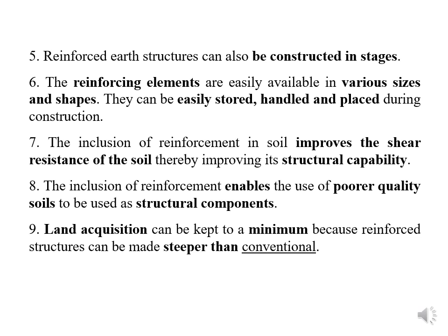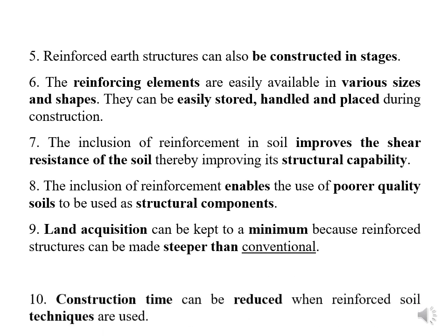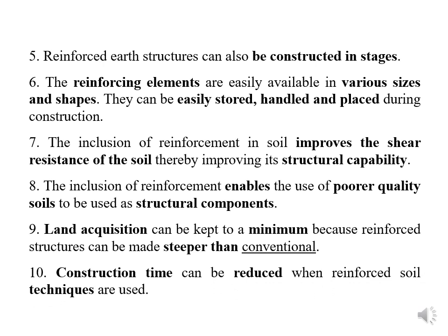Land acquisition can be kept to a minimum. What does it mean? If you construct an earth dam without reinforcement, you need a thicker earth dam. But if you use the reinforcement along with the soil, in that case thickness can be reduced. That benefit is there. Construction time can be reduced when reinforced soil techniques are used. So these are the 10 advantages of soil reinforcement.